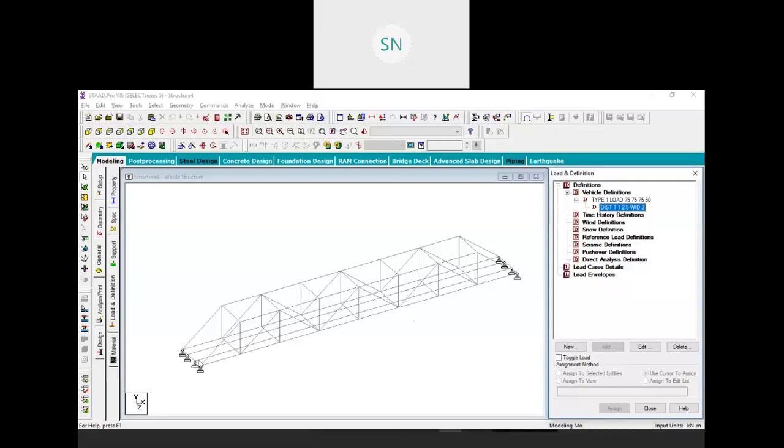So for example, I want to put my vehicle at every 0.5 meter interval. So first I will place it here, then analyze this. Then next I will place it 0.5 meter away and analyze this. Again 0.5 meter. So in this way it will take around 100 simulations to reach this point, because this is 50-meter length and I want to analyze it every 0.5 meter. So we need 100 vehicle analysis results, right?